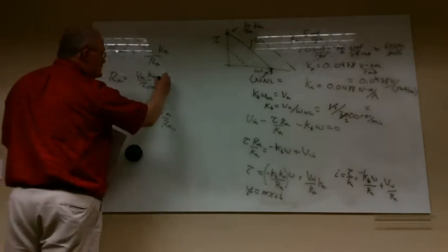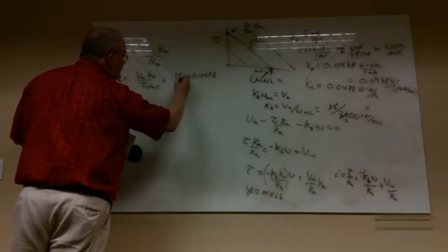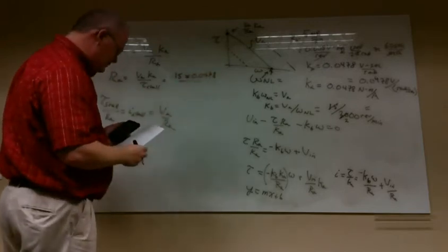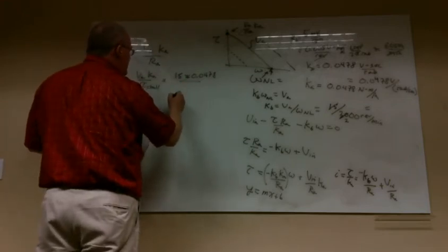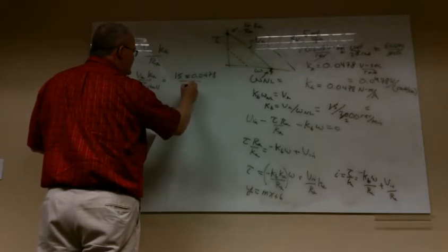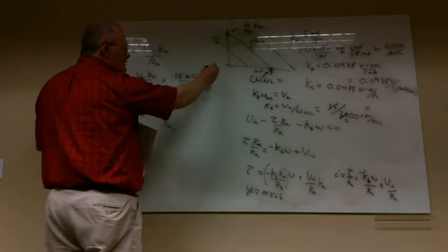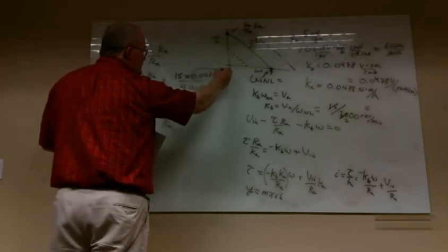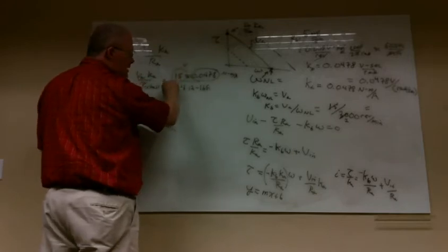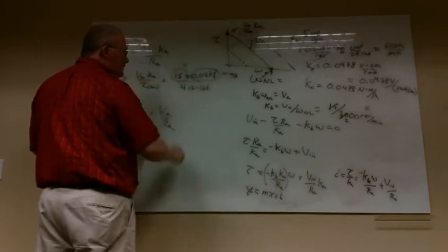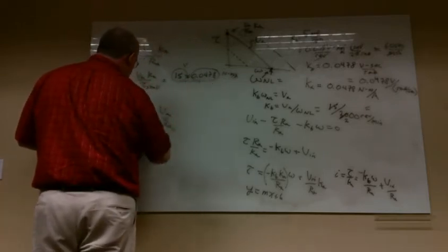And so this in our case is going to be 15 times 0.0478 divided by, what did I say tau stall was? About 4 inch-pounds. There is our problem, isn't it? Trouble is, this one is newton meters per amp, and this one's in volts. That's no problem. Newton meters per amp is no problem. That's the problem: 4 inch-pounds force. Okay, so how do we deal with that?